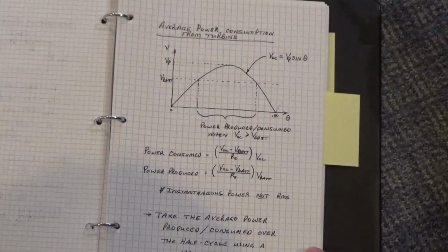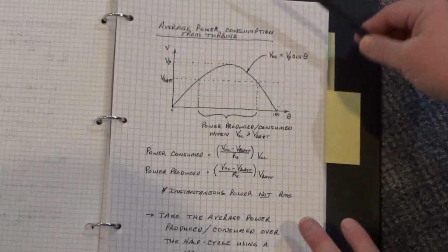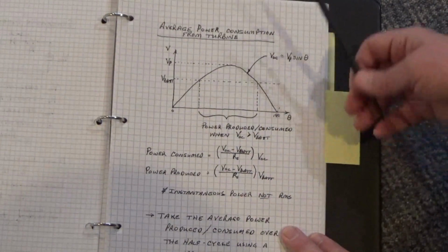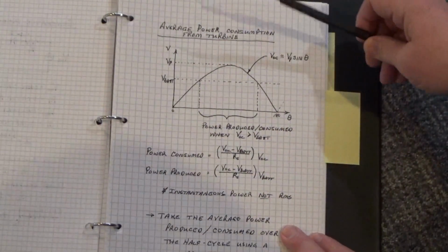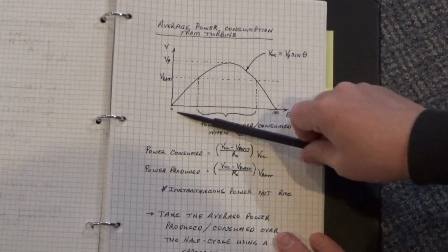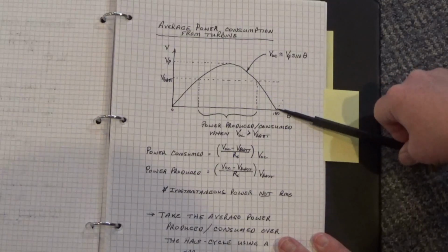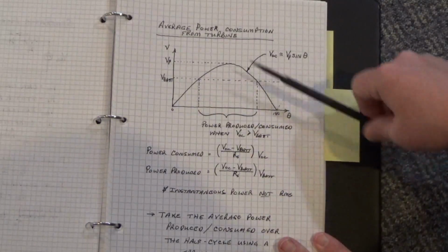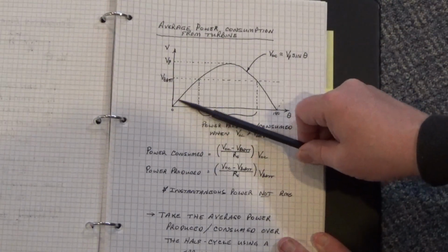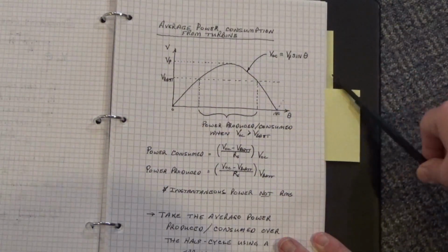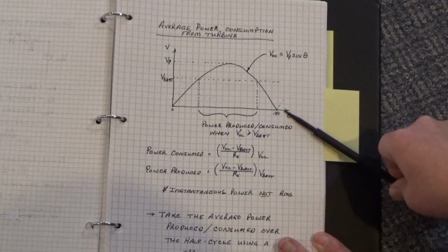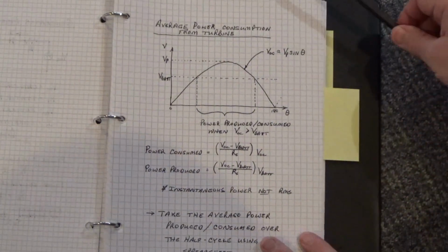Okay, so I'm assuming that I'm going to have a sinusoidal waveform. That might not be true. Like if you had widely spaced magnets, you might just get voltage spikes. In this case, I don't think I'm going to get that. I think I'm going to get close to a sinusoidal waveform. And I'm just assuming it's full wave rectified, so it goes like this and then just repeats. So it goes for 180 degrees of the phase cycle and then just repeats.